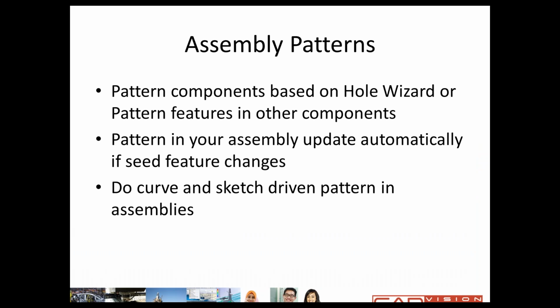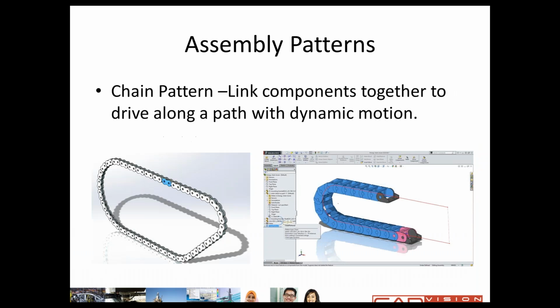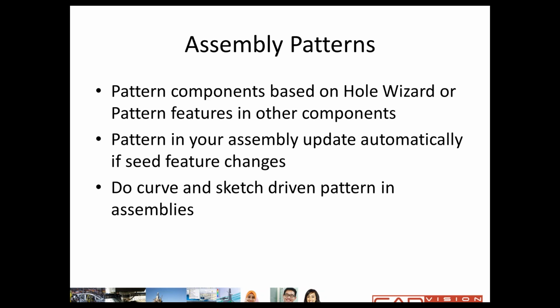Next is assembly patterns. You can pattern components based on hole results, or pattern features in other components. Patterns in your assemblies update automatically if the seed feature changes. New in 2014, you can do curve and sketch driven patterns in assemblies. They were only available in parts until 2014. In 2013 you could not do that, and 2012 as well.